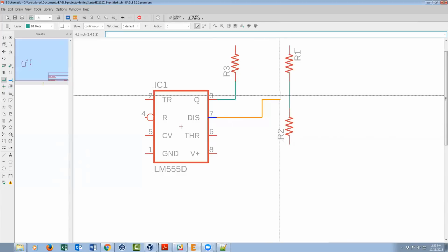So I left click. When I left click on the intersection, you automatically get the dot. So you never have to place a dot yourself. If you find yourself wanting to place a dot manually, you're doing something wrong, because the net command will place them automatically for you. It's quite possible you're off grid. Right. That's why the grid is so important on the schematic editor.